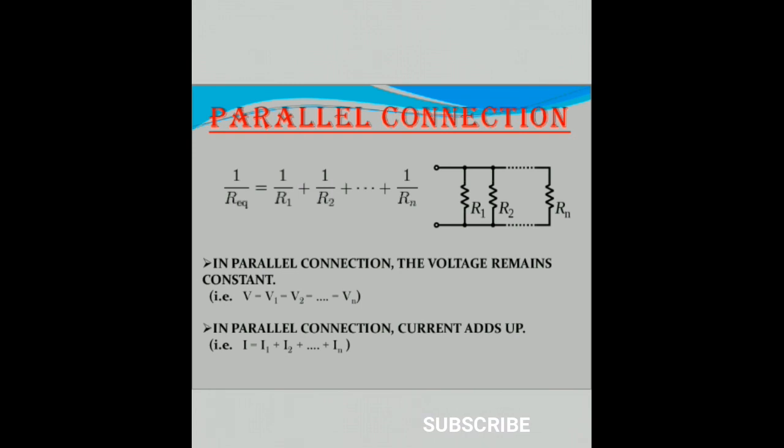Then we will discuss the parallel connection. In the parallel connection you are seeing the pictorial representation, that is R1, R2 up to Rn. These are all connected in parallel. You see how the resistors are connected in parallel in this picture. If the resistors are connected in parallel, the formula is 1 by R equivalent equals 1 by R1 plus 1 by R2 plus dot dot dot up to 1 by Rn, because n resistors are connected in parallel.